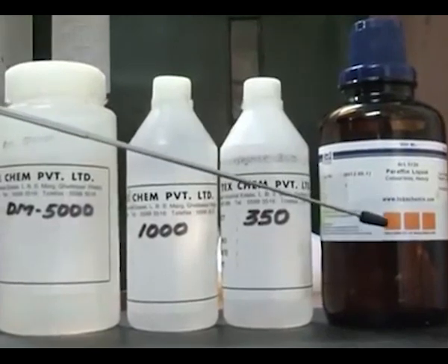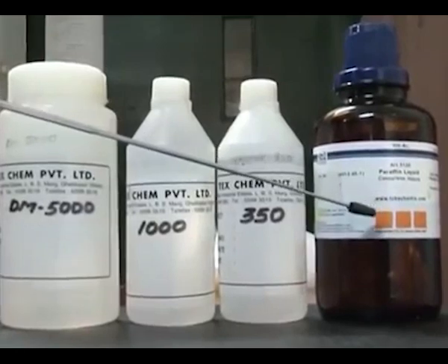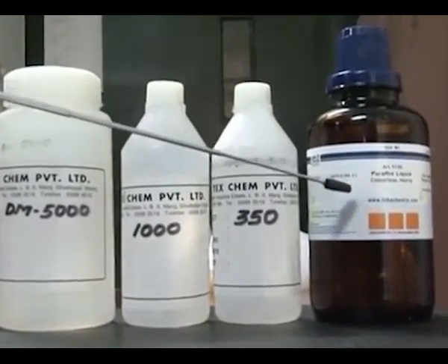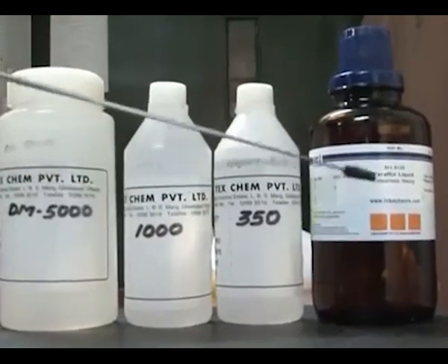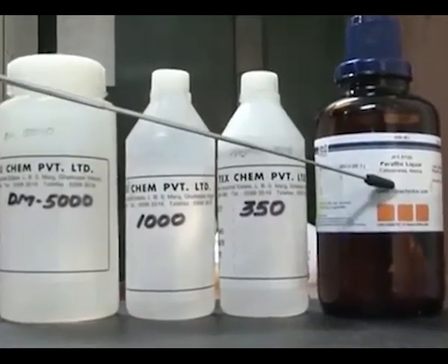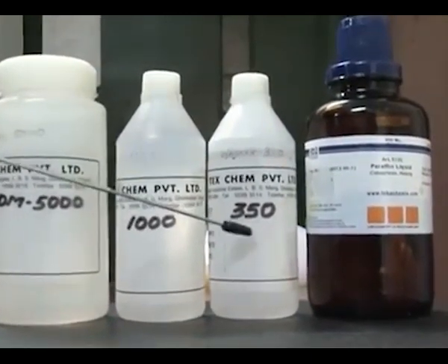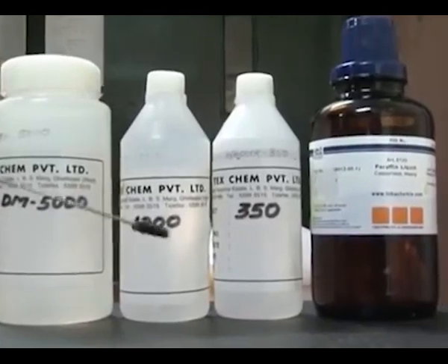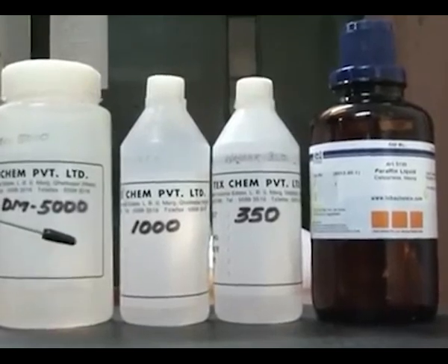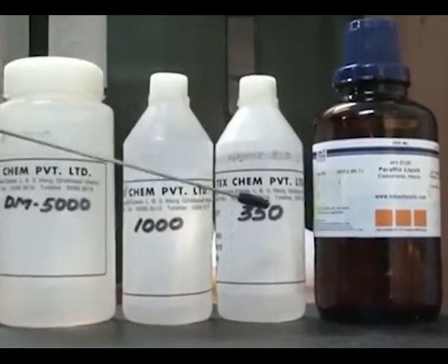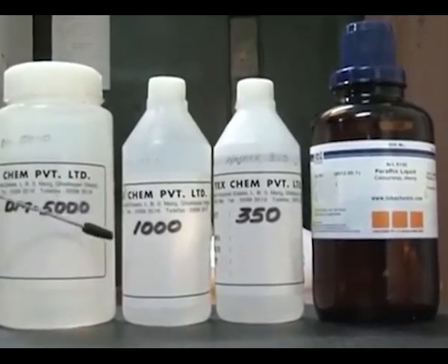The second major ingredient in the polymer rheological medium is rheological additives. In the rheological additives, we have the plasticizers. These are all the plasticizers with varying viscosities. This is the first plasticizer, that is a paraffinic oil, and these are the second plasticizers, silicone oil of different viscosities. You can see the 350 centipoise, 1000 centipoise and 5000 centipoise. This is the high viscous silicone oil and this is the low viscous silicone oil. These are the plasticizers in the present process of making the medium.